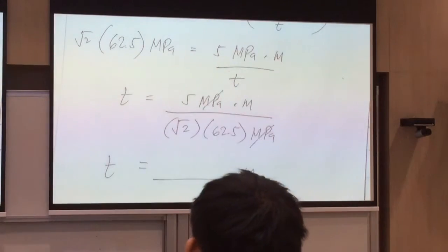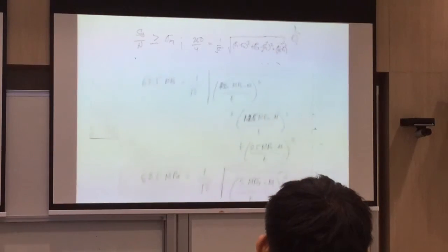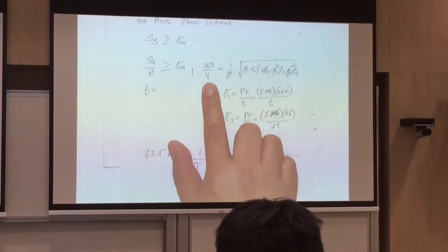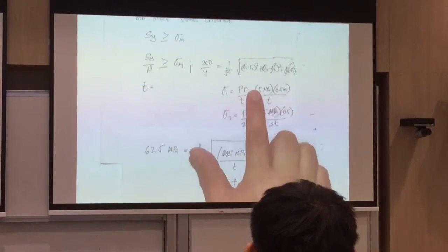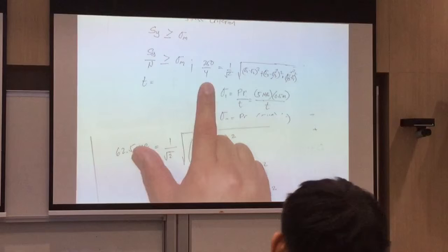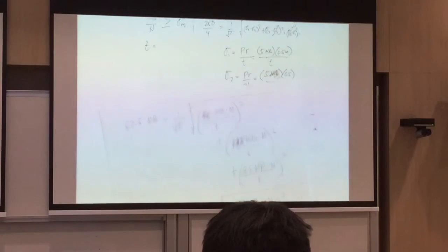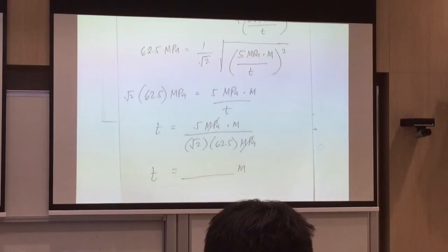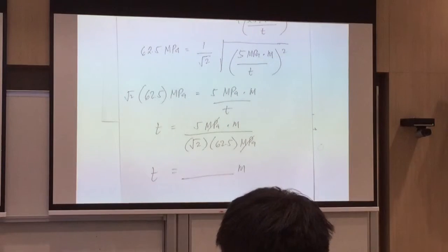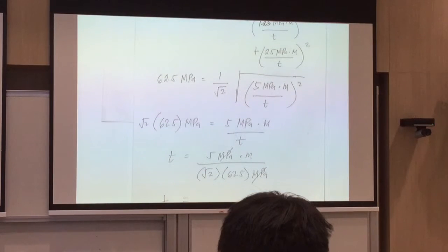So please check if my solution is correct. Please look at the steps. But this will be basically the procedure wherein you equate your working or design stress or design strength to the stress that you needed. So in this case, we're equating this yield divided by a safety factor, equating it to the von Mises stress. Okay, and then from here you can get your thickness. Chances are, since this one is a very general problem, in reality, the safety factor for the principal stress is higher than the safety factor for the von Mises stress criteria.